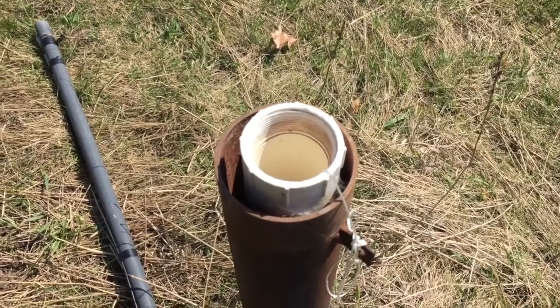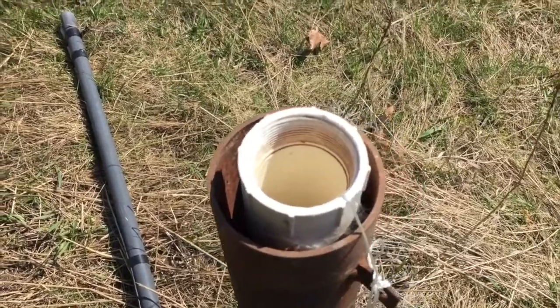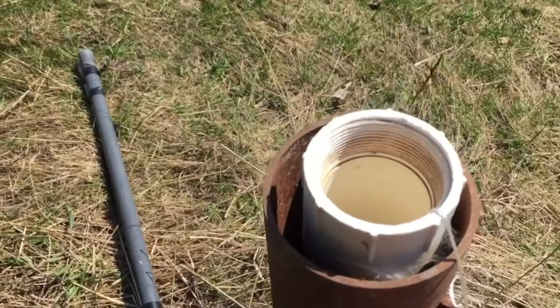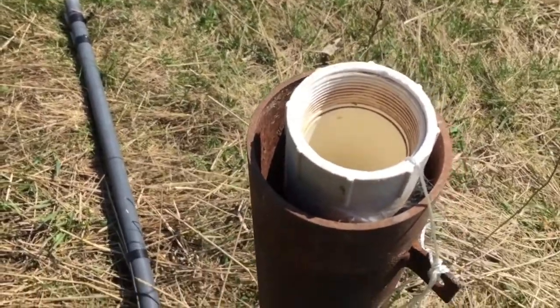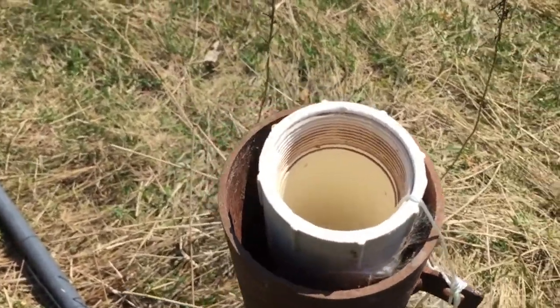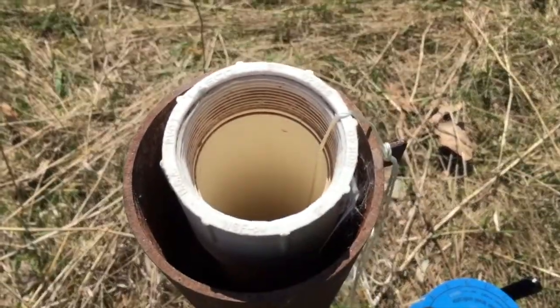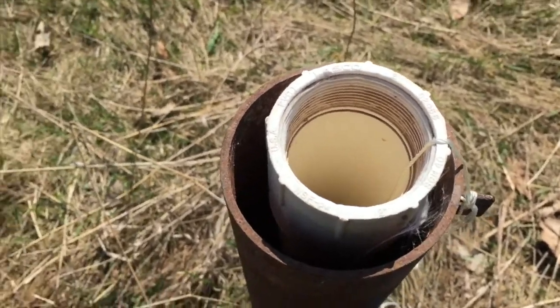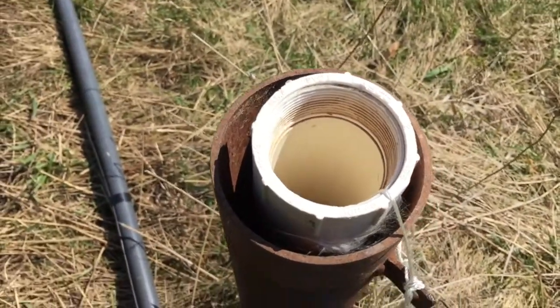Here's what it looks like with the data logger tied onto the string into the well. You can see I've tied it onto some sort of an eyelet here. That's the lock where the cap would have a lock go through. But there's plenty of space inside the well here for that slug to fit in a 2-inch PVC monitoring well. So this should be an acceptable setup for us to do our slug test.